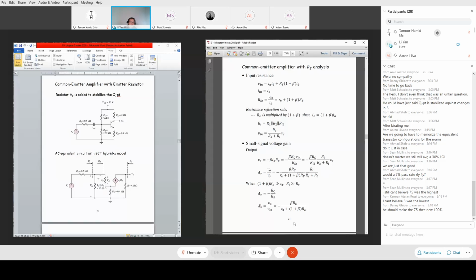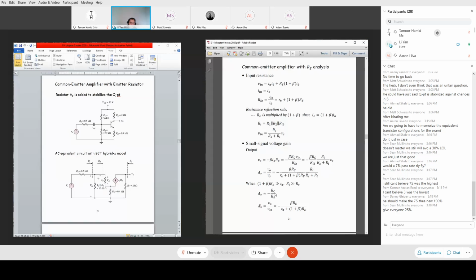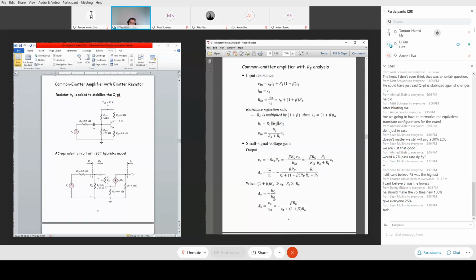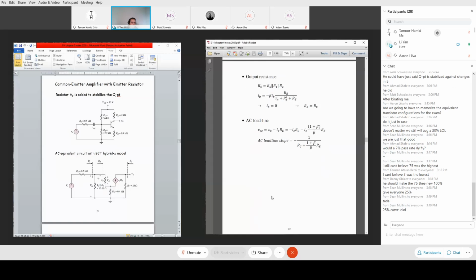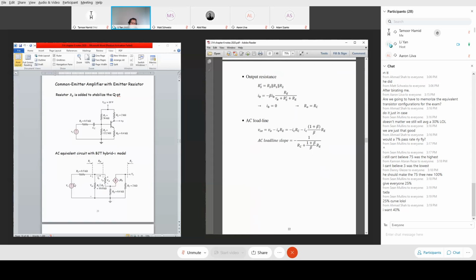So this is the role played by the resistance RE. Once you choose this, then the output voltage is simply related to the input voltage by the ratio of RC and RE. Okay. Next, how do we figure out the equivalent output resistance, viewed from here into the circuit? We want the output resistance for this whole circuit. But when you want to figure out the equivalent resistance, you have to deactivate the independent source. So V sub S should be set equal to 0 because the voltage source is deactivated.